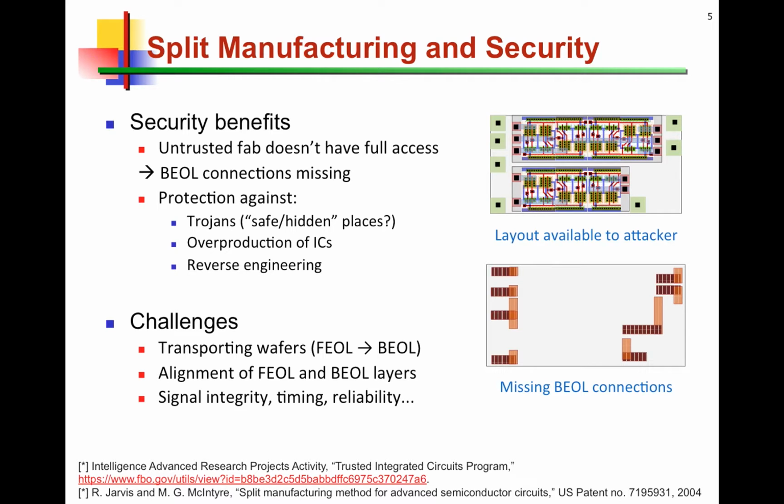All sorts of problems regarding signal integrity, timing, reliability. So these are the challenges associated with split manufacturing, but yet IARPA announces that they've made significant progress with split manufacturing, and they've successfully implemented split manufacturing for 130 nanometer technology.